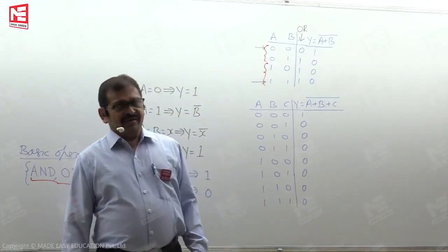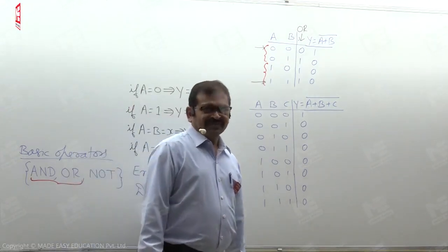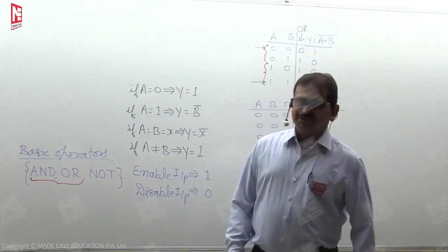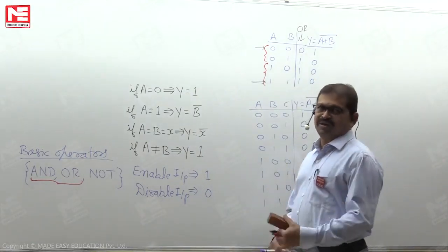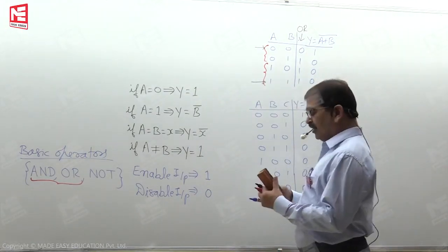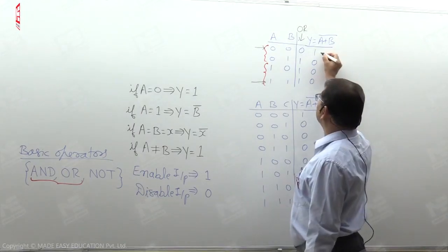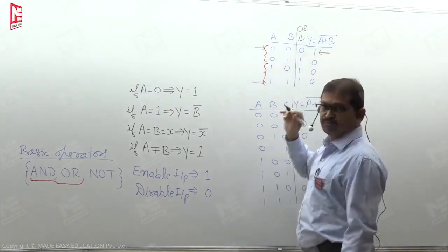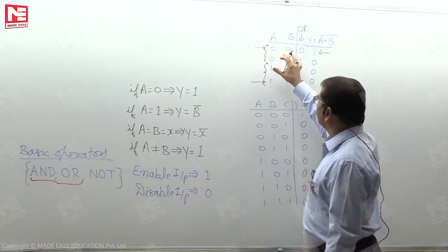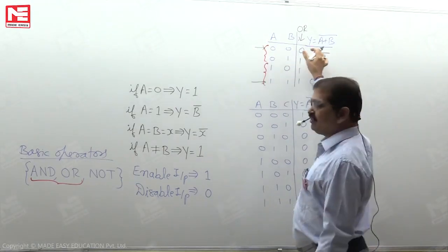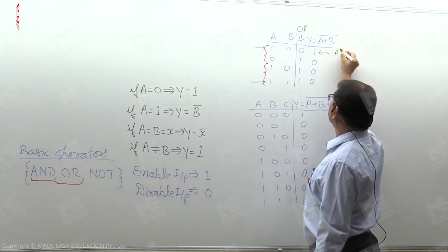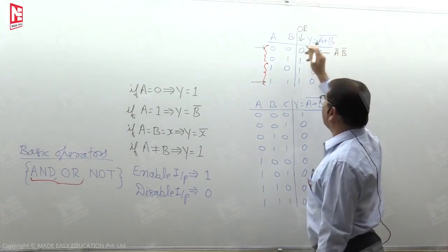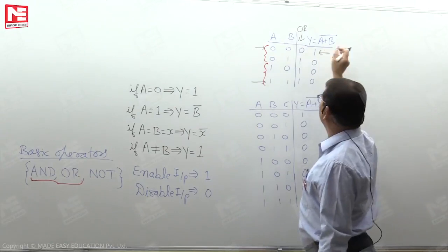Okay. Here also, the knowledge of SOP expression, if you try to look to the SOP expression on 2 variable NOR operation, to read the SOP expression, we must refer to the combinations where the function output is 1. Of course, it is the only one combination where we are having the function output is 1. As a product, if you read here, it must be A complement, B complement, because A is 0, B is 0.